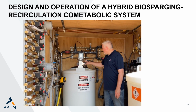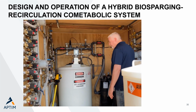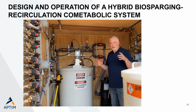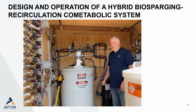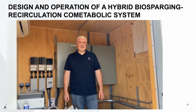So this will be added again through a peristaltic pump. It's added to the beginning of the system where it runs through all the filters, all the piping, and into each of the 5 injection wells, enough to fill each of those wells and the borehole volume around it. And then we stop pumping for the next 12 hours. And that inhibits the biological growth throughout the system as well as in the injection well.